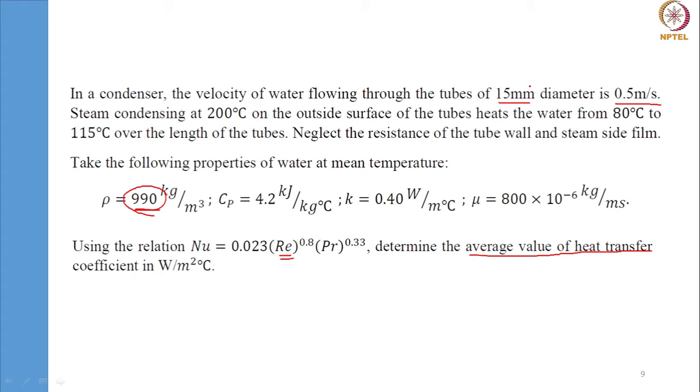You get a value of Reynolds number as 9281.85. Once you get that, one term on our right hand side is done. We are interested to find out the Prandtl number. Prandtl number is defined as mu Cp by K. Again, after knowing the mathematical form, it's just arithmetic now. You plug the values of mu, Cp of water, and K of water.